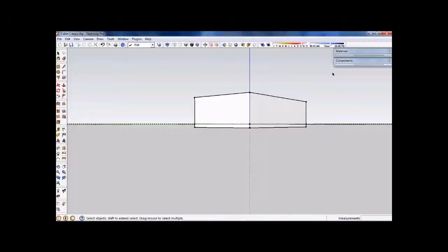I'll get you to click out here on the right hand side and press and hold, don't let go, and drag a window through such that the other side, when you let it go, will be past the extents of the building, however it will be above that floor level plane.